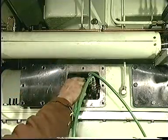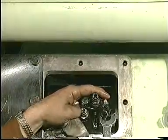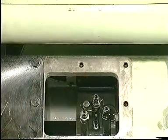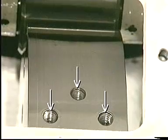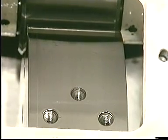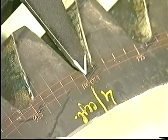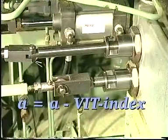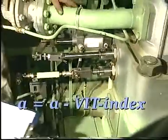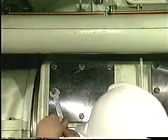Relieve the system of pressure and remove the spanner and hydraulic tools. Leave the cams to settle for a minimum of 15 minutes and then mount the plugs. Turn the cylinder concerned to top dead center and read the new fuel pump lead. Read the VIT index. If the VIT index is not at 0, the lead must be corrected before it is recorded in the engine logbook. Mount the cover of the camshaft housing.